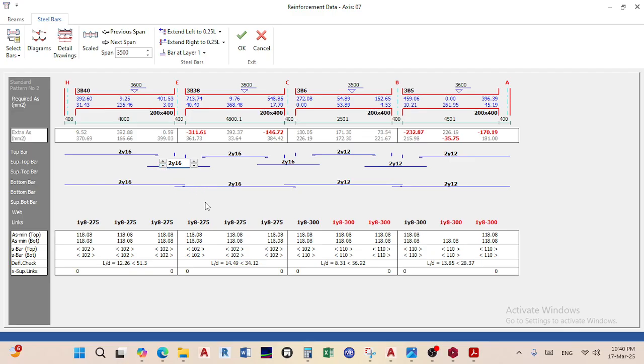Still, if it does that, okay, go to the bottom. Only the bottom numbers change. And if you want, okay, put three. So where can we add more reinforcement? Can we add it here? It's changing. Okay, so in the middle we put three Y16s, and then at the top there, like that. Also we can do the same here. You add two extra. Okay.